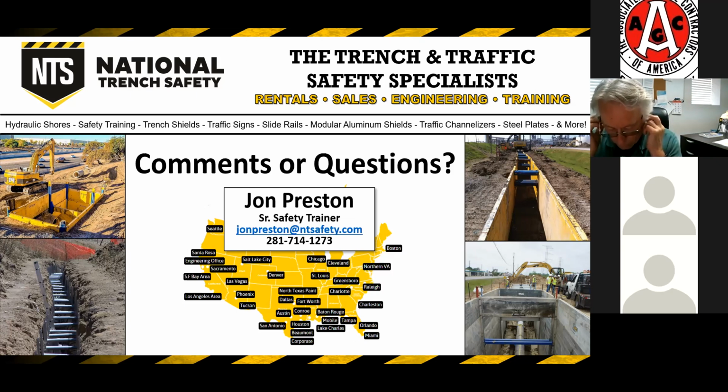John, Mike Jones's question: when it comes to surcharge loading and utilizing hydraulic shoring, would you agree the tabulated data should give you the limits of what the shoring system is rated for? Yes, the tabulated data should provide that, but if it's not there, the manufacturer should be able to provide it as well. Excellent point.